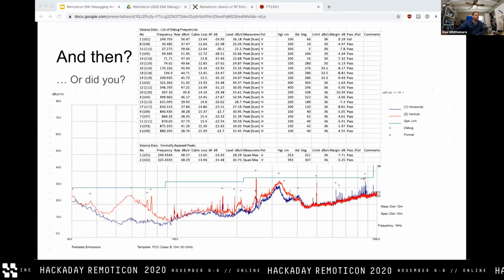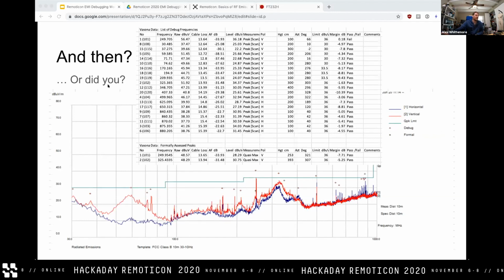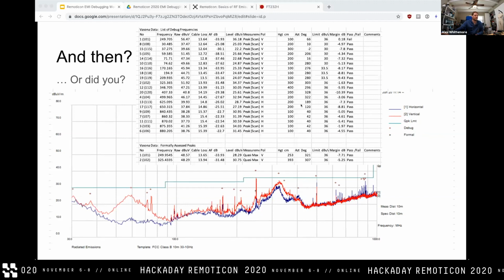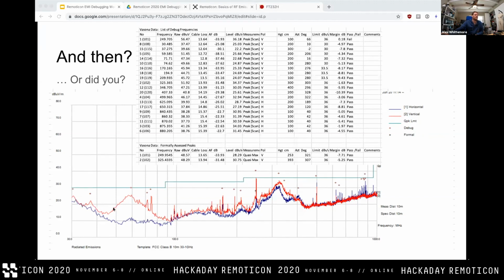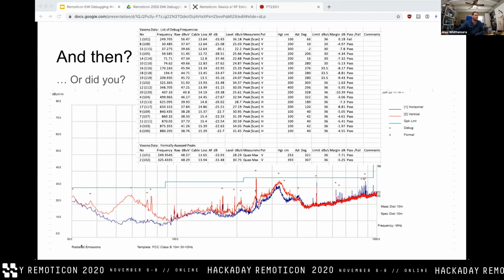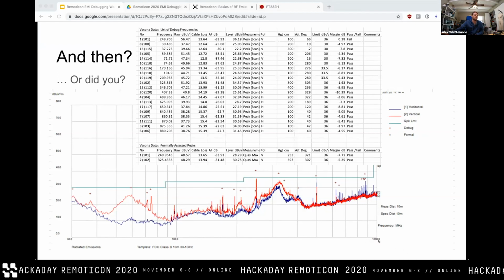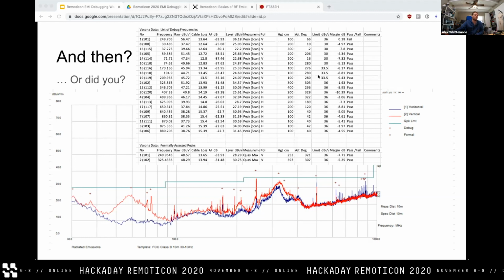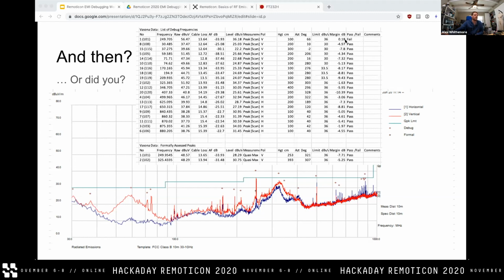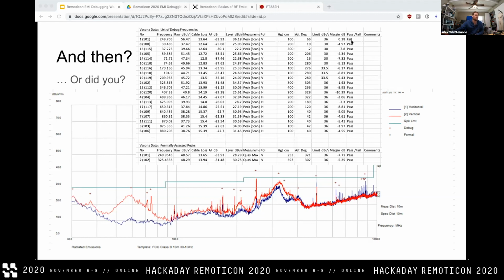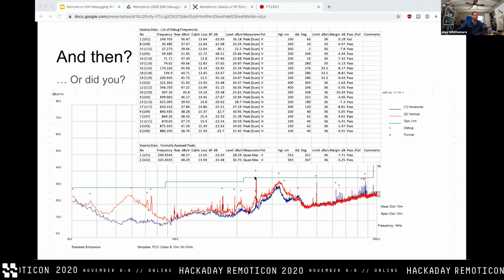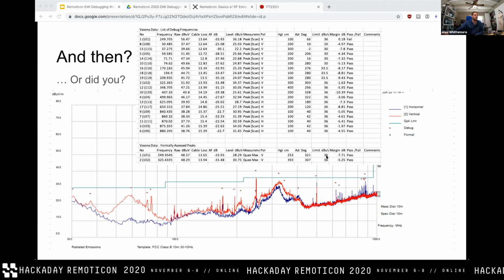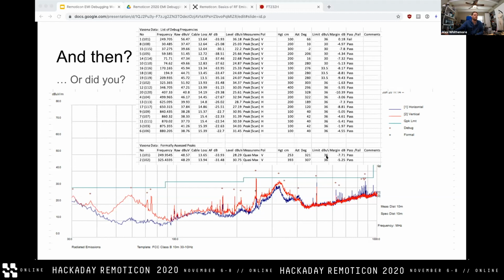And I guess I jumped the gun describing all of that because the next slide was, did you actually fail? And the answer was on a lot of those peaks, no. This is an example from that same 30 megahertz to 1 gigahertz spectrum, where the product has at least one, actually in this case, there's only one limit line violation at that 250 megahertz. That's still a problem.